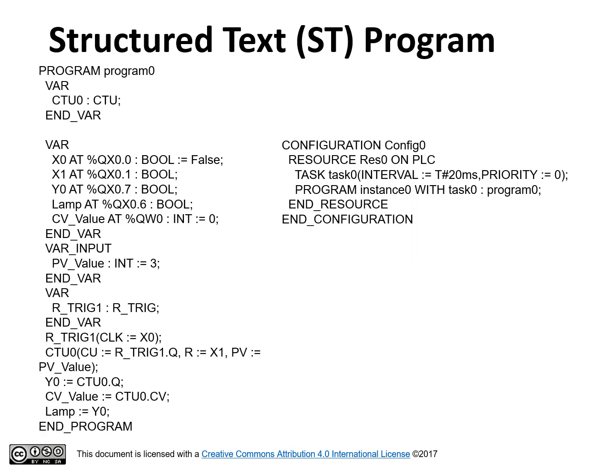The application using ladder logic diagram LD is designed using the OpenPLC editor. After completing the LD program, a structured text ST program is generated that will subsequently be loaded into the simulated PLC using the OpenPLC runtime interface. The ST program is shown in the figure. For those who have programmed using the Pascal language, this should look familiar.